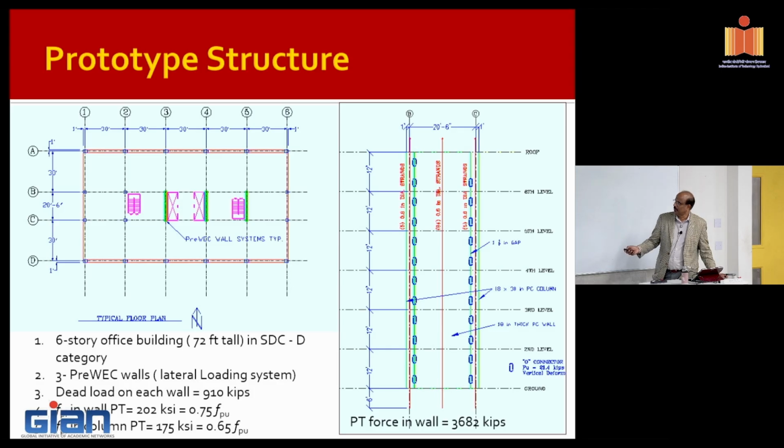So these floors can be attached directly to these frames, but this interior load has to be transferred to the outer frame as well. At least half of that comes here, half of that goes here. So once you make this seismic frame, you only design this to be the seismic frame, and the rest of the frame, you see it's a column, there may be a beam running here.